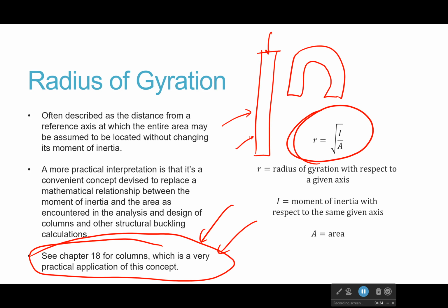The material itself is fine, but it begins to deform and bend because slight variations, slight imperfections cause it to bend one way or the other, and it can't stop itself. It's just not stable. So that's what the radius of gyration gets to. And in this case, it's just going to be the square root of our moment of inertia over the area of our cross section. Okay? Moment of inertia over the area of our cross section.